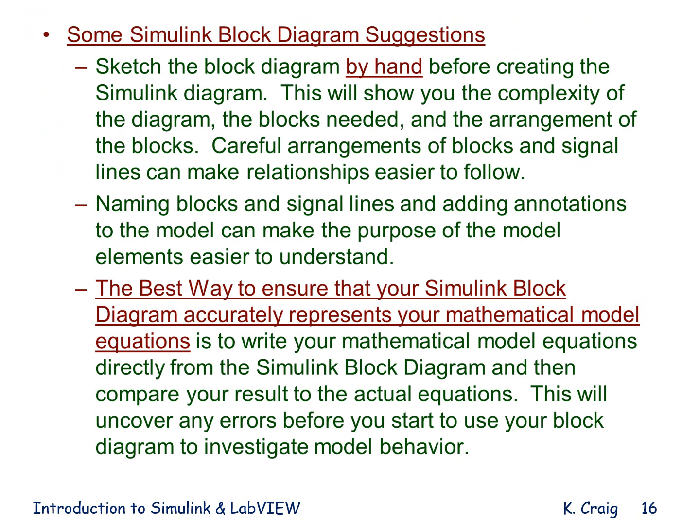Here are some Simulink block diagram suggestions. Always sketch the block diagram by hand before creating the Simulink diagram. I certainly did that in this case. I didn't show it to you, but I did it. And the reason we do that is to show the complexity of the diagram, the blocks needed, and the arrangement of blocks, because careful arrangement of blocks and signal lines can make relationships easier to follow.